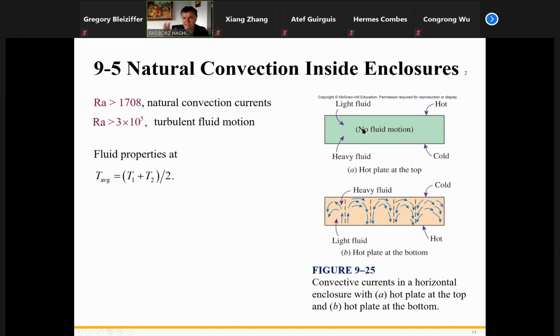Please understand the physics again. If you have a cold plate and a hot ceiling heated up there, you have no convection. The only heat transfer is by radiation. And you can sometimes see it in some warehouses. In some warehouses, for the workers, they put a sort of heating element on top of their heads.